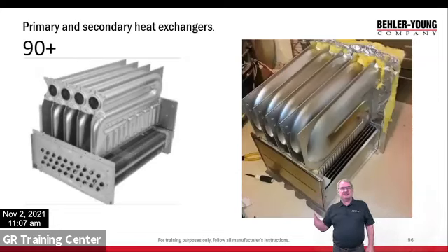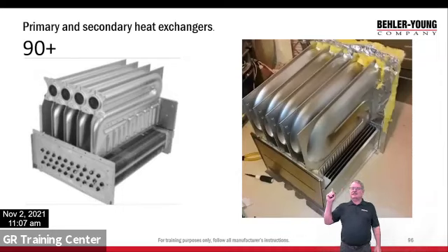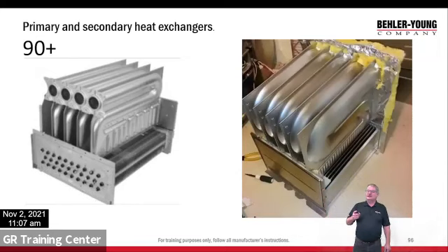You look at the one over there, it's actually like a coil. And here it's really narrow little fins. And the blower is right underneath that. So the cool house air coming from the blower is going to hit the secondary heat exchanger first, which is about 250 degrees. All right. Going to cool that, and then it's going to go across the hotter part of the heat exchanger. All right.